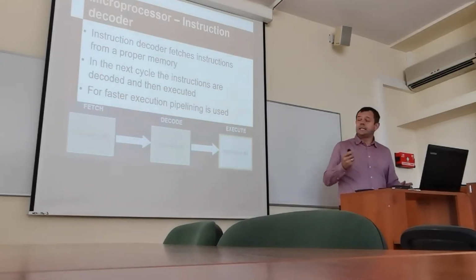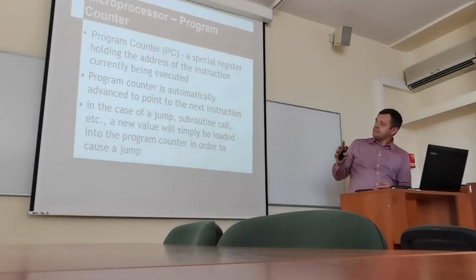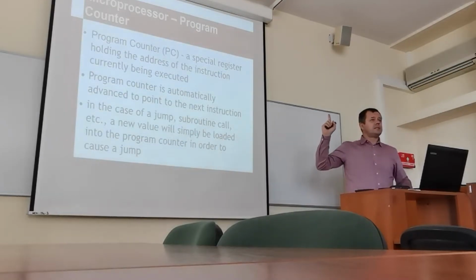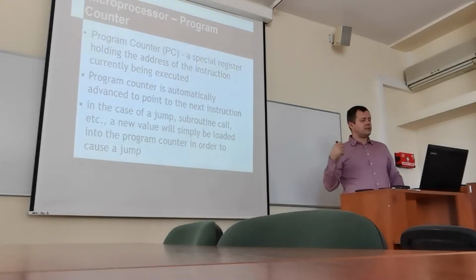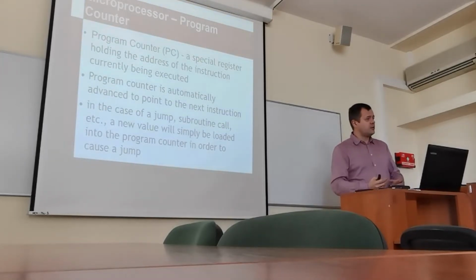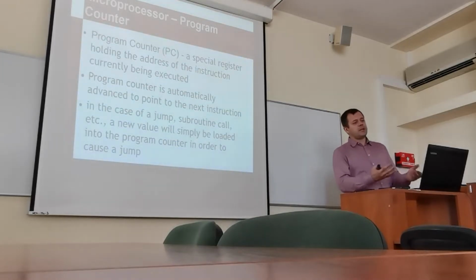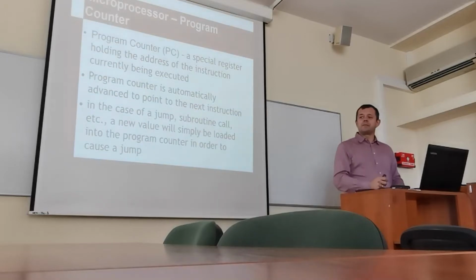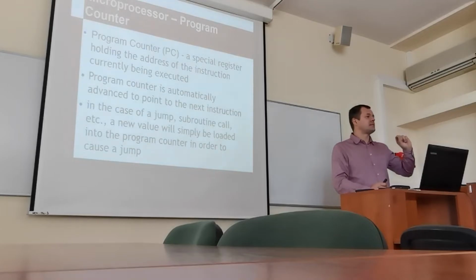Usually one register. One small remark. The width of A, B, and R on the slide that I showed a bit before, the width of those signals defines if the microcontroller is 8-bit, 16-bit, or 32-bit. Thus, the width of the program counter tells us the addressing space of the microprocessor.